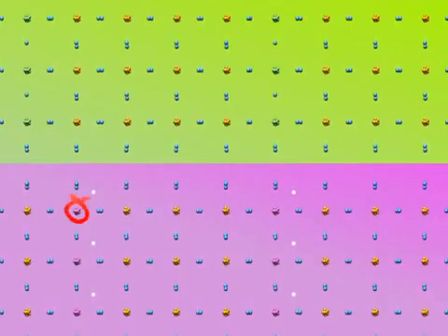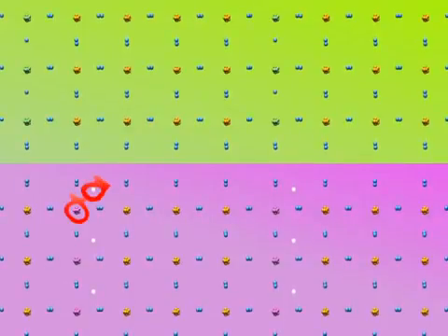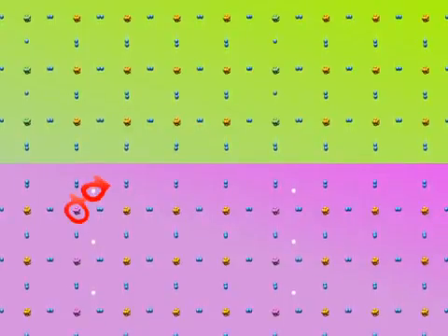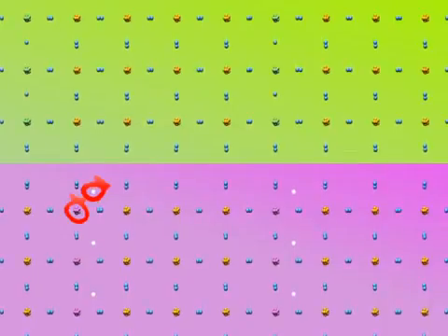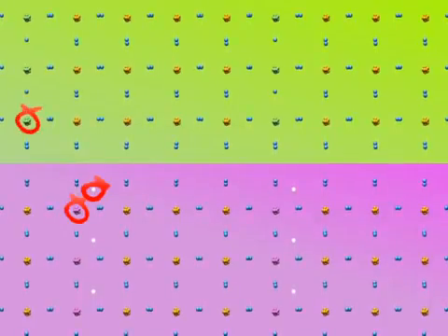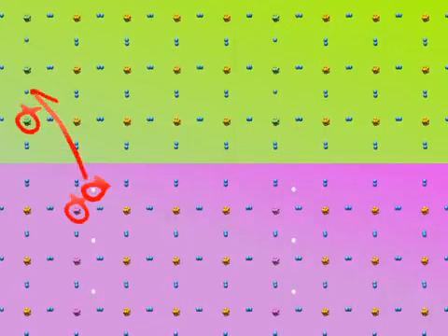When different doped layers are placed in contact with each other, the basic structure of a transistor is born. One layer is doped with phosphorus atoms, which provide extra electrons. These electrons are free. The other layer is doped with boron atoms, which have only 3 valence electrons. That way, holes are created. A free electron of the n-type layer is recombining with the hole of the p-type layer, resulting in a hole in the n-type layer. This will happen to other electrons.